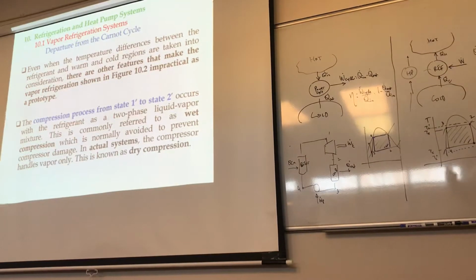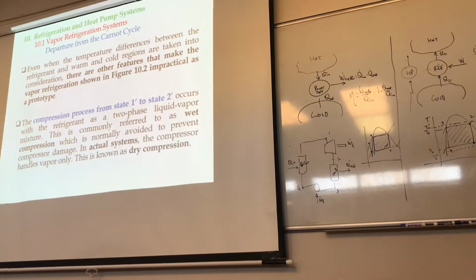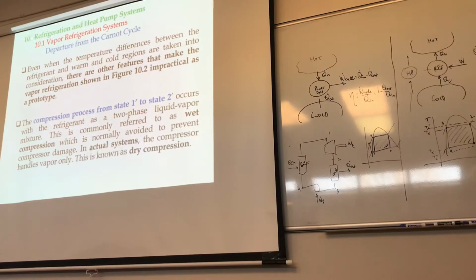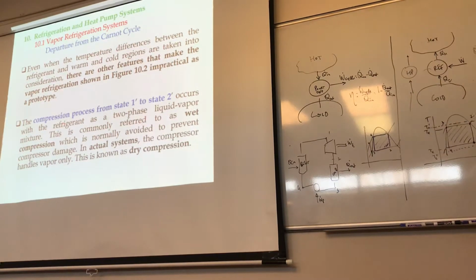It's impractical. Why? First of all, the compression process, as I go from 1 to 2, occurs with the refrigerant under the dome, as a two-phase liquid-vapor mixture.